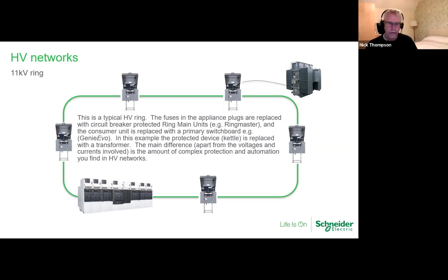We're going to step down from the HV, in this case, it's 11 kV, into the transformer, and then you're going to step down to more manageable for a commercial or domestic application, i.e. the transformer. Now, the cables will be routed wherever it's practical to go. So you'll find cables running underneath the pavement outside your own home, outside the office. You may even have, if you're HV cables, routed inside a large complex. So it's like oil and gas, or data center, or even hospitals will have their own HV networks.